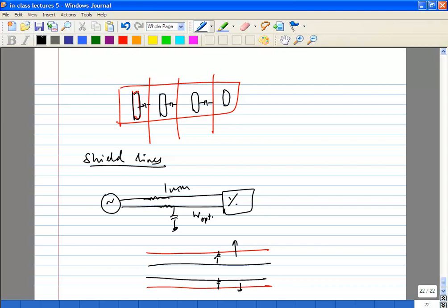There will be metal lines. Okay, so let's say this is on M3. So these will also be on M3. Okay, you can actually make a multi-layer shield also. For example, if this is on M3, you can add shield on top on M2, on M4, and shield on bottom on M2 also. So you can basically make it a square thing.